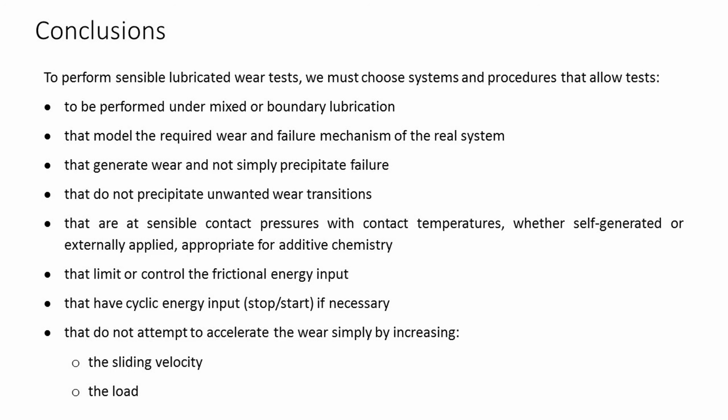And so to conclusions. In order to perform sensible lubricated wear tests, we must choose systems and procedures that allow tests to be performed under mixed or boundary lubrication, that model the required wear or failure mechanism of the real system, that generate wear and do not simply precipitate failure, that do not precipitate unwanted wear transitions, that are at a sensible contact pressure with contact temperatures, whether self-generated or externally applied, appropriate for the additive chemistry, that limit or control the frictional energy input, that have cyclic energy input, including stop-starts, if necessary, that do not attempt to accelerate the wear simply by increasing the sliding velocity or the load.